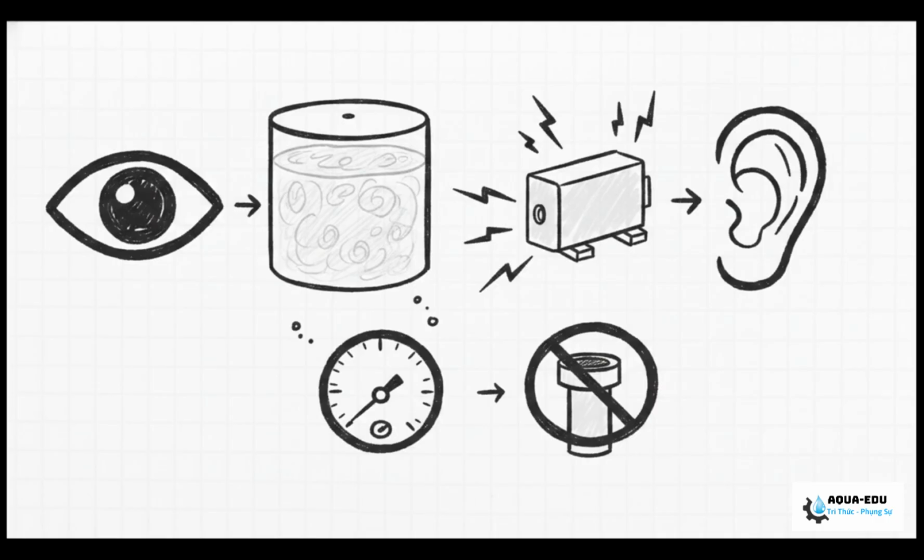And pay close attention to your equipment. Is the saturator pressure gauge dipping below that crucial 4-bar mark? Is the PR pump, the pressure recycle pump, screaming at you, vibrating, or running ridiculously hot? Check the recycle flow meter, too. Is it showing a massive drop from your typical 10 to 30% design ratio? And, maybe most critically, if you don't hear that familiar, steady, hissing sound of air releasing from the nozzles, you have a major issue on your hands.